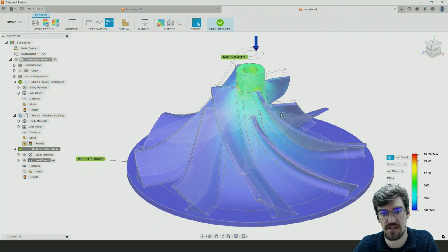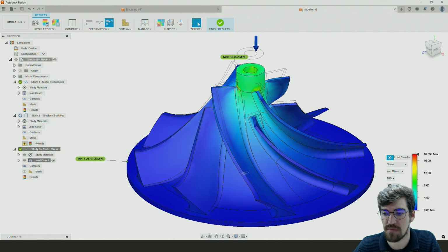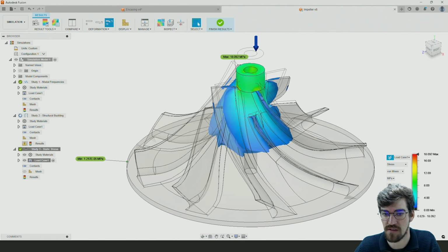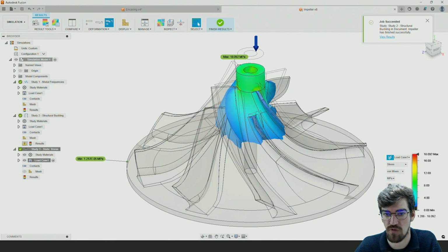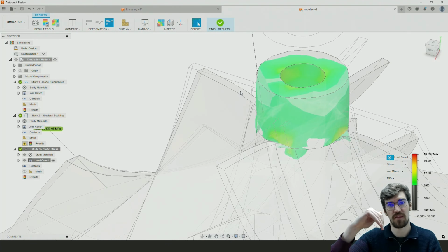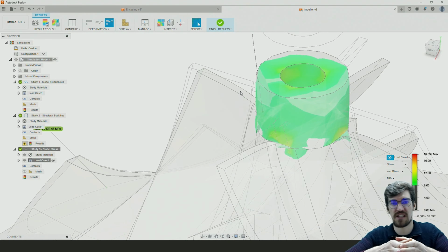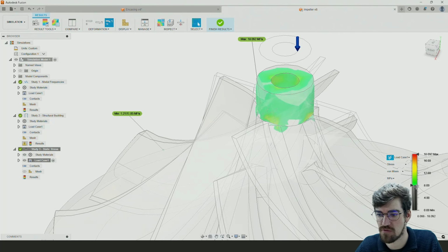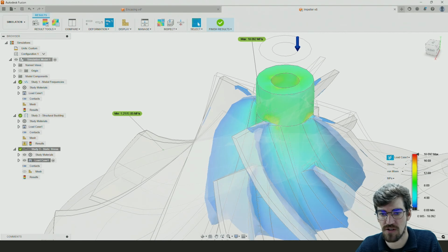We can also start to bring the areas down. We've got a volume in here which is colored based on the stress that's associated to that particular part of the surface. So if I say, well, I'm not worried about anything that is below 8 megapascals, so I'm going to reduce the area that it shows me within here. We can then start to remove any material that is less than 8 all the way up to that point over there, and I can see that most of the stress, as I would probably expect, is where the force itself is being applied. So we've got a really small surface area that's absorbing all of the 50 kilograms on there, and then distributing that very quickly throughout the component itself, and it reduces, as we can see, very quickly as it goes throughout the rest of the part.